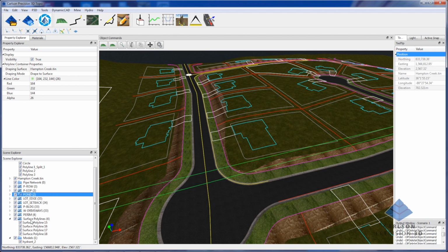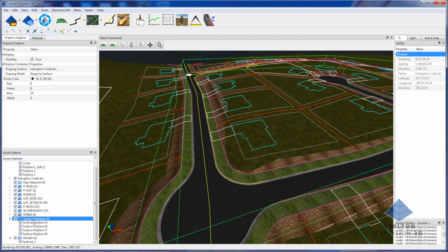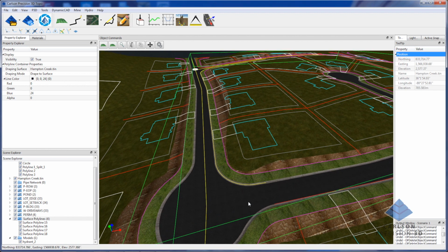And then if you happen to go in and want to rename one of these, you can rename it, and then you can also change the default color for those objects in there. So that's basically how you control your layer names and your colors for the polylines. So in the DXF, you would see pretty much what you see here. You'd see all these different colored polylines, and they'd all be on these different layers.